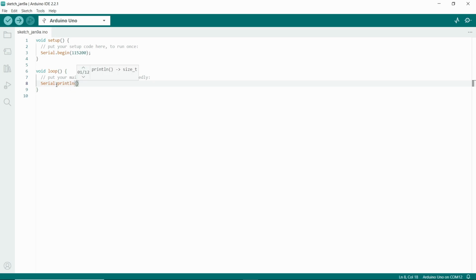And then I'm going to use the function that is available by default called analogRead. I'm going to use the first pin, let me check, it's A0, the first analog pin on my Arduino. And then, as I've said before, I'm supplying the Arduino with 5 volts, so I'm going to multiply the value by 5, and then, as the values that the ADC reads are 10 bits, I'm going to divide by 1023. Okay, I can close this.